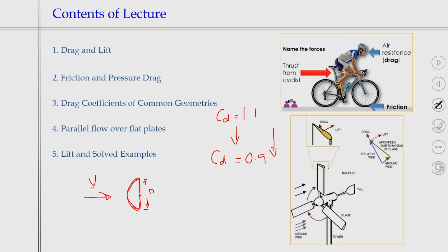So, if you do it, you will get a CD value equal to 0.4. That is the CD value. If you have the velocity like this and a half semicircle, not going into details, it is considered Reynolds numbers greater than 10 to the power 4 in the turbulent regions. So, we have the CD value equal to 0.4.